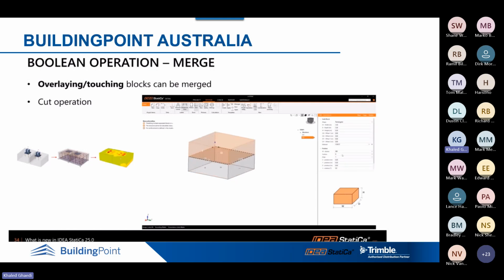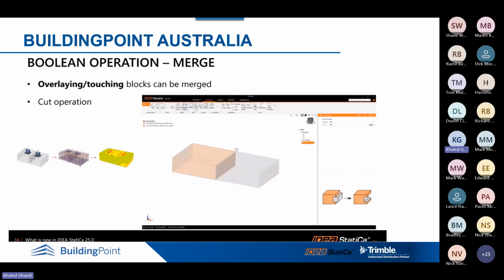And also, as we said, we have the merge option for multiple concrete blocks. Using this option, you can just merge the overlapping and touching blocks like this. Or in some cases, maybe you have a uniform concrete block and you want to cut it, so you can use the cut operation, and just like here, you can separate the concrete block as well. So this is what we have in IDEA StatiCa 25.